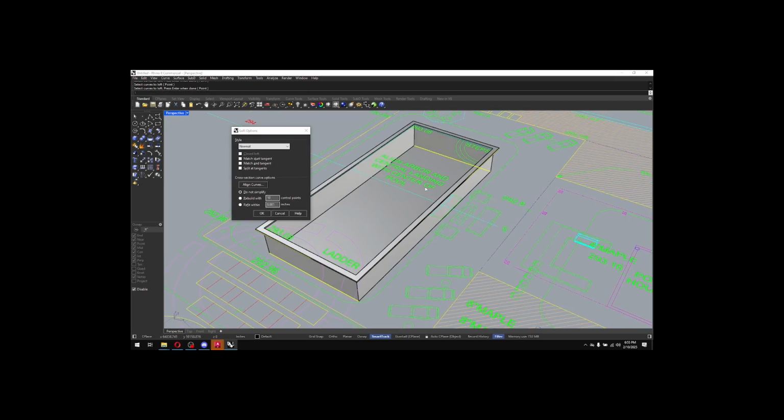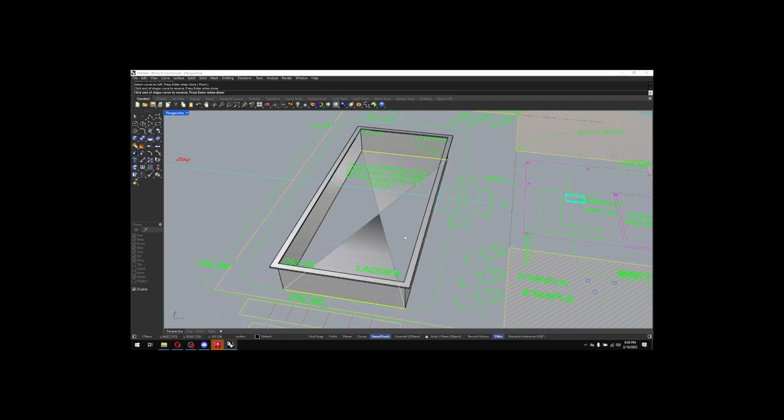This one's flat. We'll look at a slightly more complicated version of this. But if all of a sudden this comes in and it looks like it's connecting, but I've twisted it, it gets a little confused sometimes, because it denotes what the start and end of a line is, and it's going to try to connect end to end, start to start. That will look like this if it's messed up. It's trying to connect this corner to that corner, so you get a weird shape. If you ever run into that, all you have to do is go to Align Curves, click on one of those, and it'll flip it. It'll know that it needs the start and the end to go to the other sides.